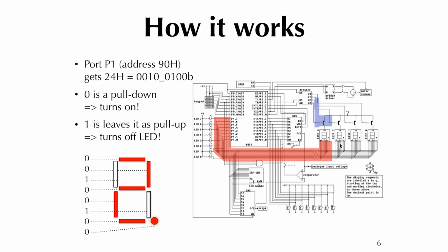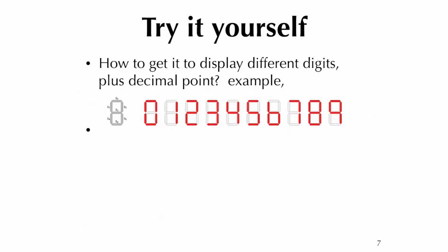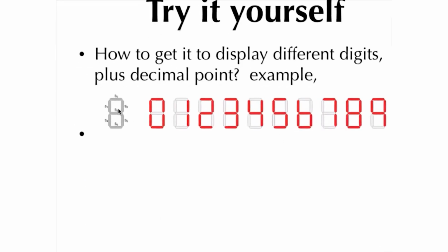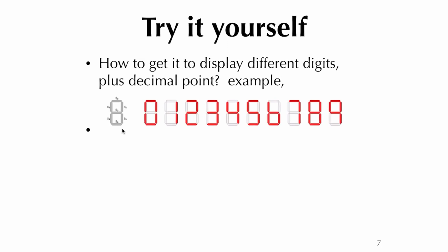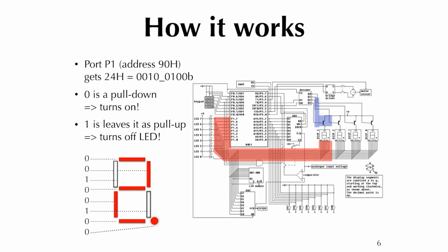How are they connected? Well, you can check the connection, right? They have these named connections. Segment 0, 1, 2, well, sorry, this is a little pixelated. 3, 4, 5, 6. So it kind of goes top, and then left, right, middle, and then the left, right, middle, and then finally the dot. There's a little decimal point, right? Okay, so there's the connection diagram.